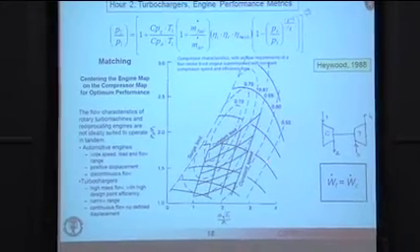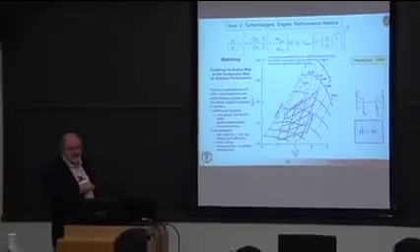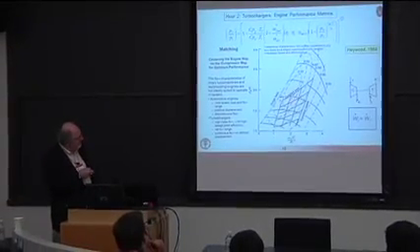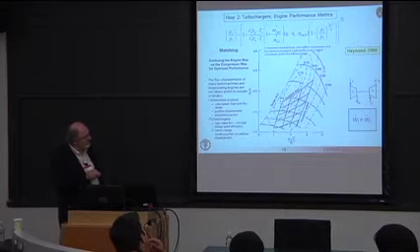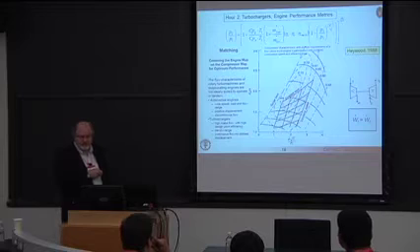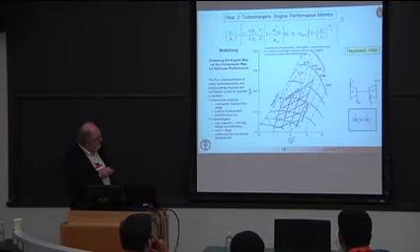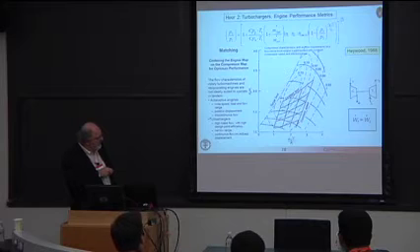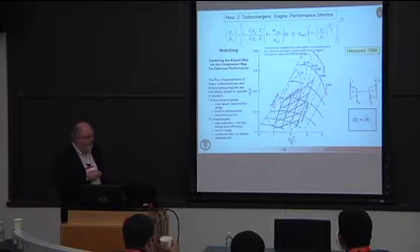And the idea is to try to get this fishing net superimposed on the other fishing net in the most optimum place, right? So remember we said that the high efficiency part of the compressor was here. So this is not a very good matching that I've shown you here. You'd want to move this whole map a little bit further up. But you've got to be very careful not to hit the surge line here or the choke line on the other side.